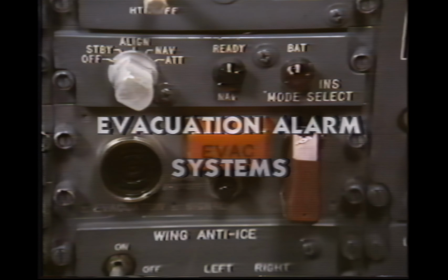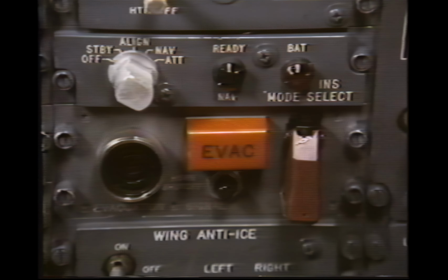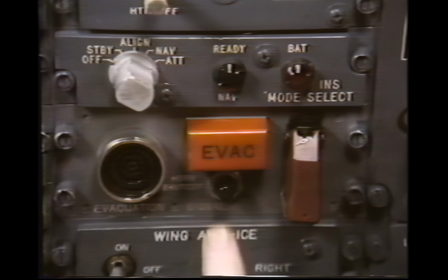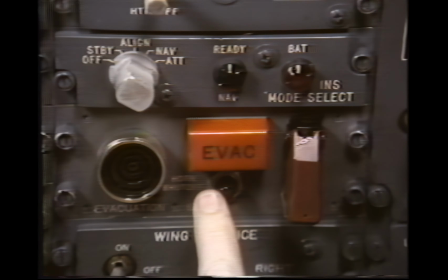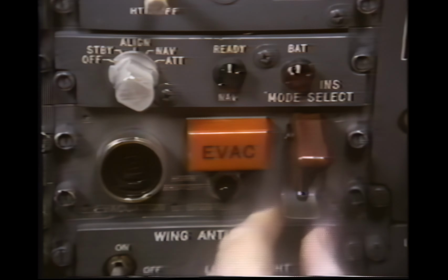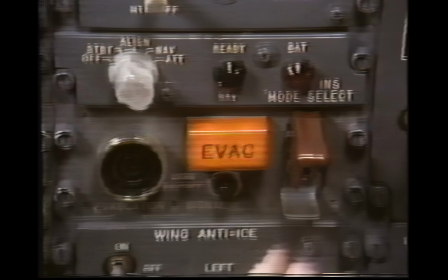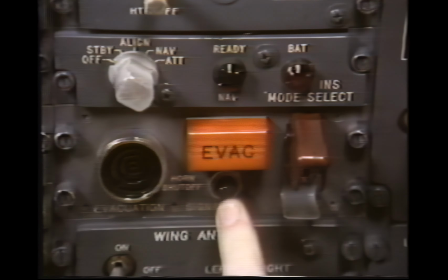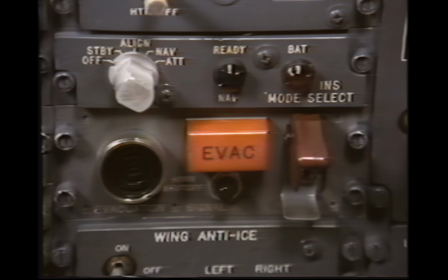An evacuation alarm panel is located at each crew station. One alarm is located in the cockpit on the pilot's overhead panel. Here's how it works. Lift this guard and push up on the switch. If the beeping noise interferes with your voice commands, it can be silenced by pushing this button. You'll notice, however, that the warning light continues to flash. There is an evacuation alarm above the flight attendant station in the upper deck cabin and adjacent to each flight attendant seat in the main cabin.